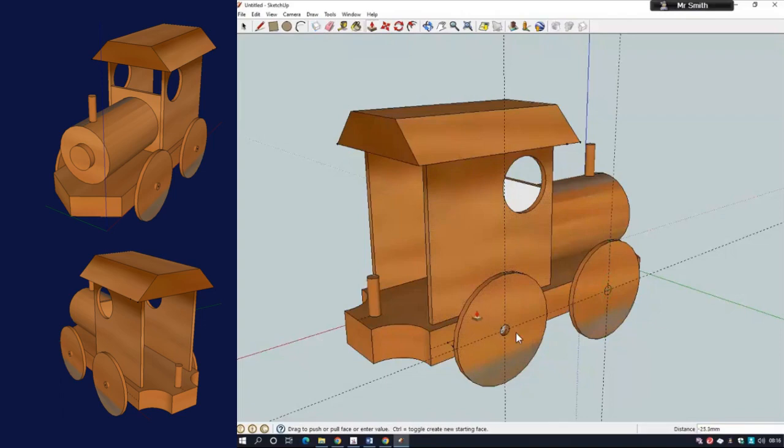Now ideally, you kind of want it going to stick all the way through. It's not quite working, so I'm going to make it come out a little bit so it looks like it sticks slightly round the wheel. I'm just going for, click on it, 2mm out, same thing here, and then repeat on the other side.